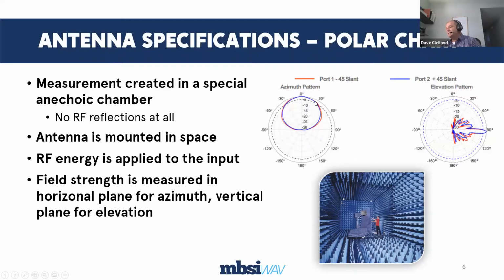So in this case, we have what looks like a 60-degree antenna, because we have 3 dB less signal at 30 degrees clockwise and 30 degrees counterclockwise from the design azimuth of the antenna. But as we keep going around in azimuth, the signal rolls off. Attenuation is increasing the farther we get away from the design direction.